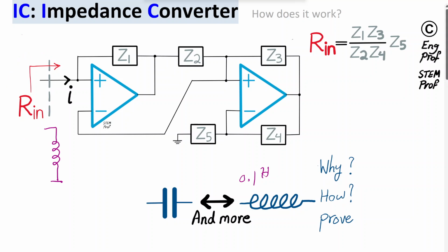Well, if from the perspective of the input terminal the circuit effectively looks like an inductor, a virtual or simulated inductor between the input node and the ground, then we would refer to this as a virtual inductor. It can be pretty large. If we can make the circuit stable, we can simulate as large as a few henries of inductor, which is very interesting. So simulating inductors and virtual impedances is one application.